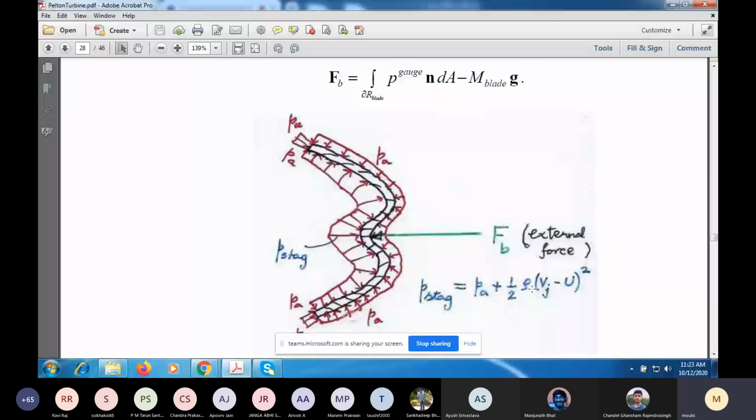But as we have seen, the flow is steady in the translating frame, and Euler's equations of motion are invariant, so they have the same form under the Galilean transformation. So we have a Bernoulli equation in the translating frame. If the flow is steady in the translating frame, you can apply Bernoulli's equation. The difference is that you have to use the relative velocity.